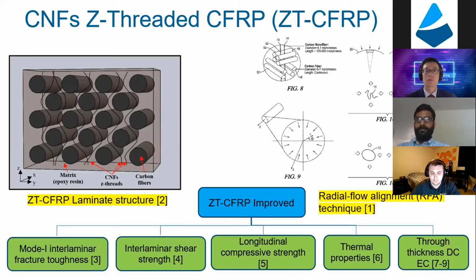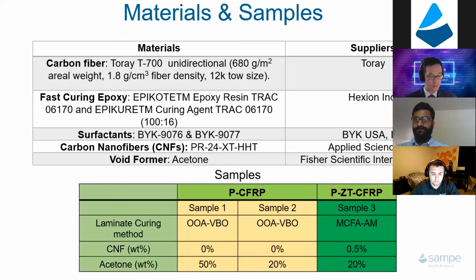So the challenge will be, first, you need to find the host resin. What type of resin you want to choose, and what kind of chemistry you want to slow down the reaction a little bit, so you can control it. You don't want it to cure, so you have enough time to disperse the nanoparticle and make the pre-preg. And then when you want to cure, it cures in 45 seconds. So that is not an easy job on the chemistry side. So we have to figure out the combination, the mixture, or maybe look for various polymer blends to achieve that. So that's one thing. And another one we are going to study is the printing itself.